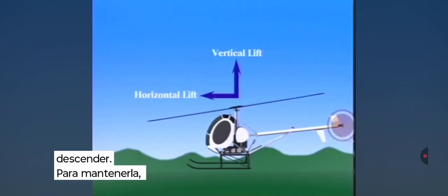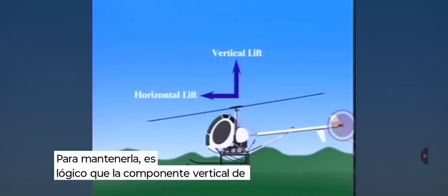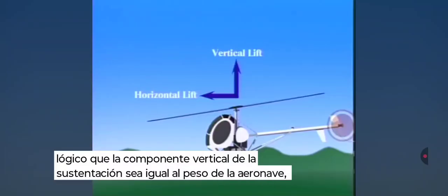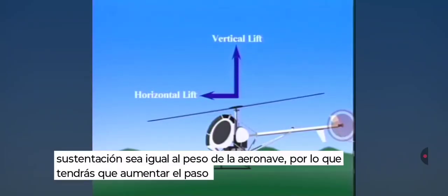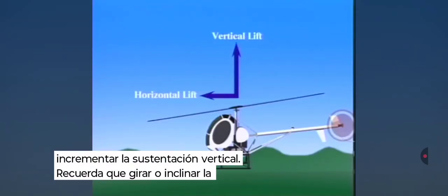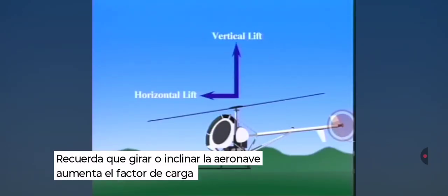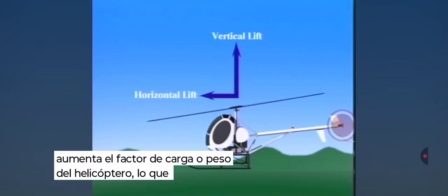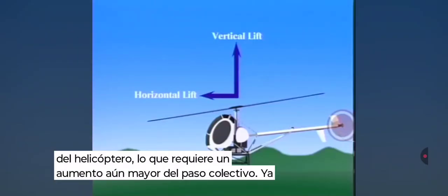In order to maintain altitude, it makes sense that the vertical component of lift must equal the aircraft's weight, so you'll need to raise the collective to increase vertical lift. And remember, turning or banking increases the load factor or weight of the helicopter, requiring even more collective increase.